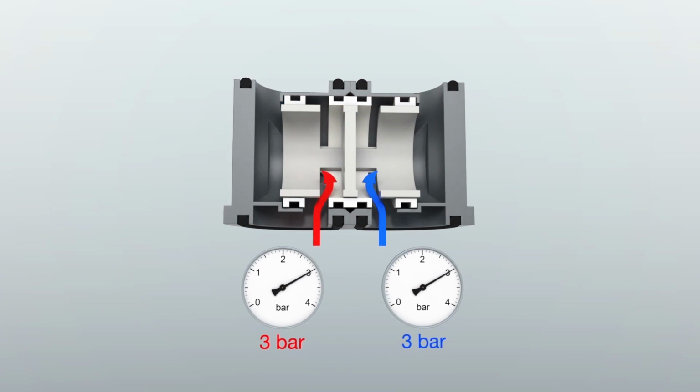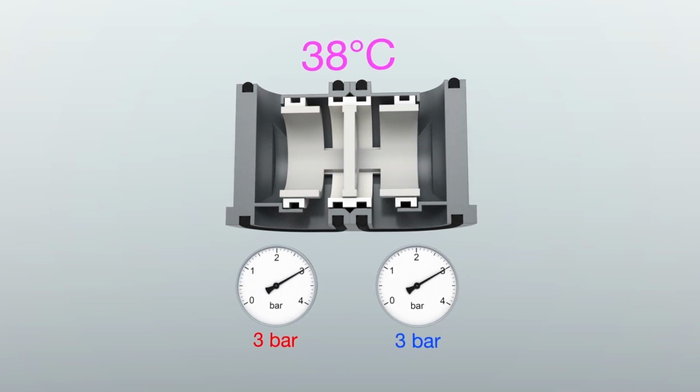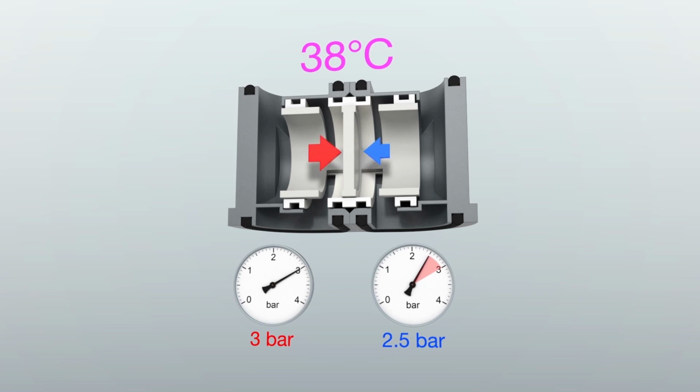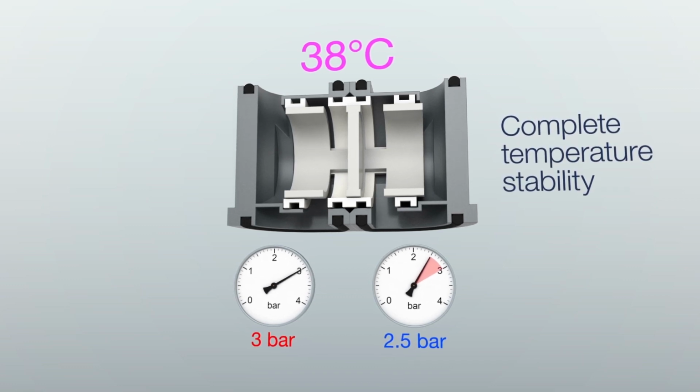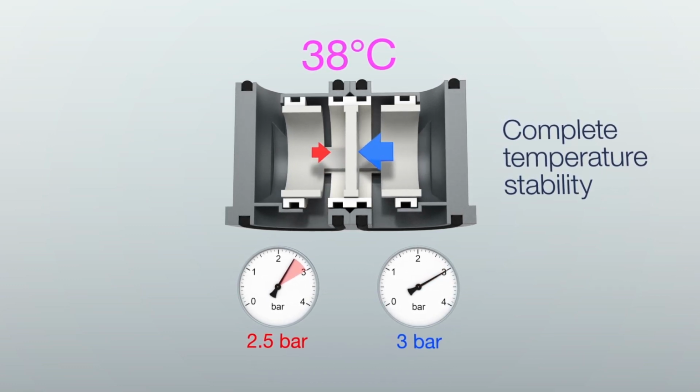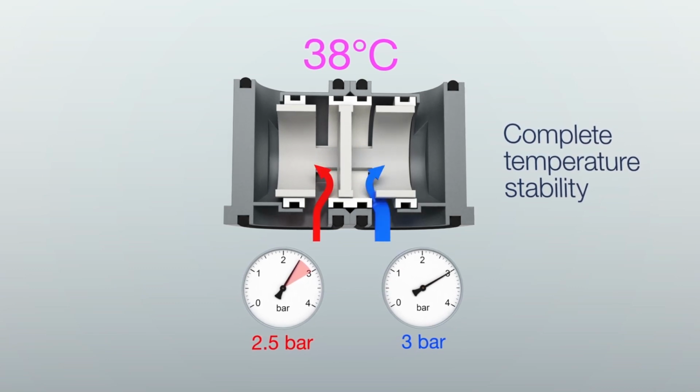At first, mechanical pressure balancing technology known as EP, which compensates for pressure variations in the system and therefore the temperature changes. This usually happens when you take a shower and in the next room a patient flushes a toilet or uses cold water to wash their hands. With EP technology, you don't feel any variation in temperature. And above all, if the cold water supply fails suddenly, the hot water shuts off almost 100%, leaving only the slightest trickle of hot water.